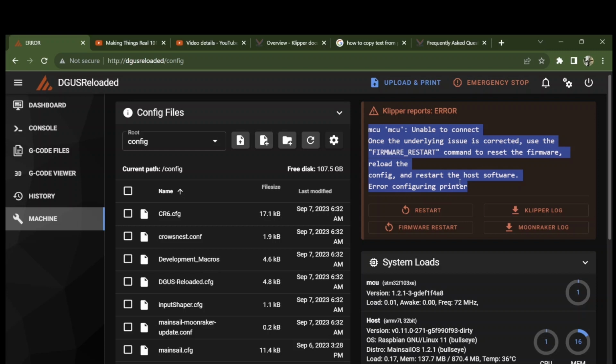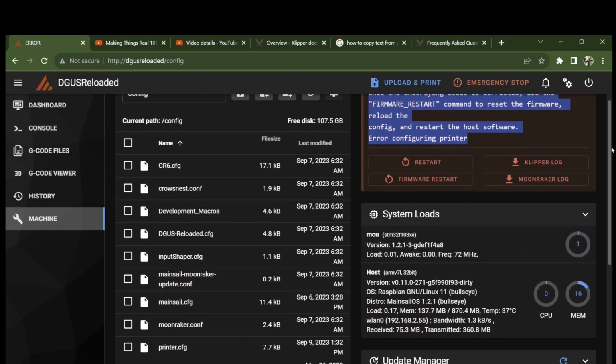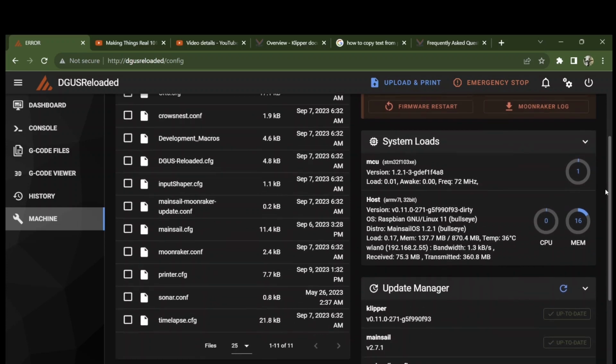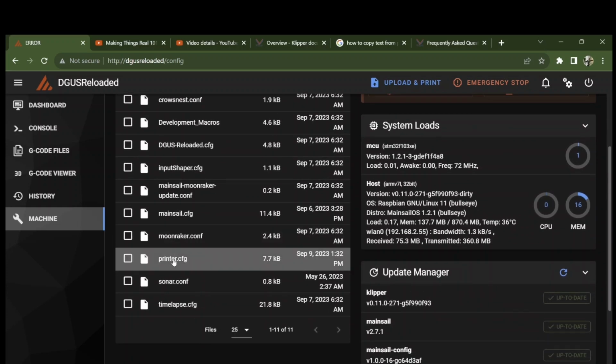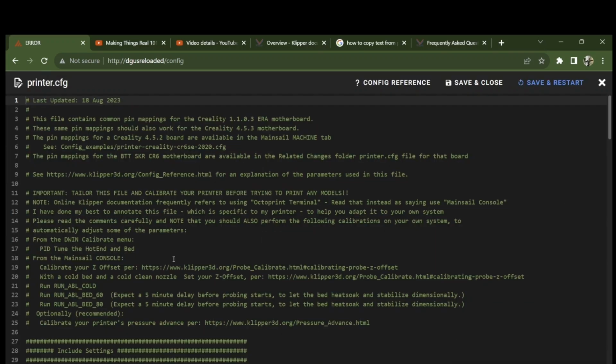It's been so long since I first installed Klipper that, of course, Klipper needs to know the serial interface of the printer. When you plug your USB cable in, the Linux operating system creates a device for it, gives it an identity, and then Klipper says, okay, so what's the ID for the printer? What you have in your printer config file right now is the ID of my printer, but that may not be the ID for yours. So if you're looking at a red message like that, again, I apologize. Let's go into printer config, and I'll start with that one.